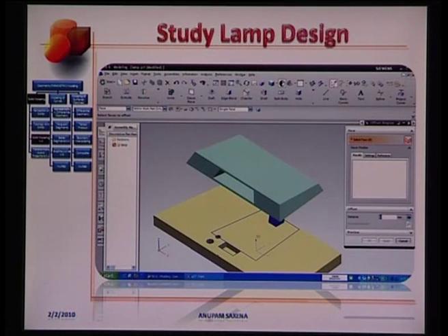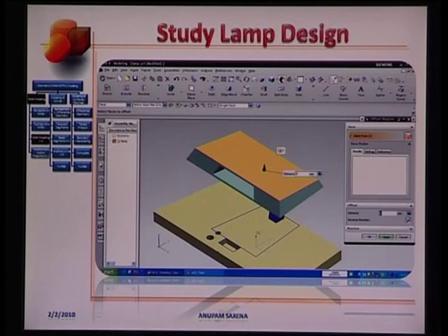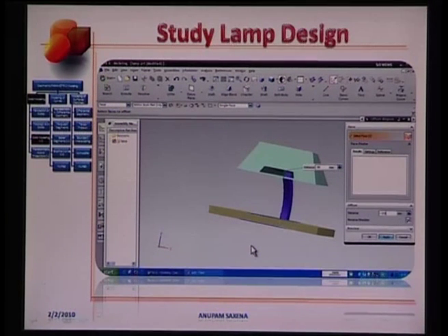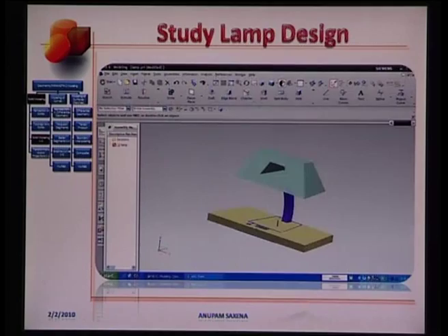We increase the vertical dimension now. Again, in a similar fashion. Choose the top face, choose the bottom face, and increase the distance between. We have left this hole right there. We can bring this hole a little upward along the vertical direction. A very similar procedure. When we do that, we have now got the hole at the right place.